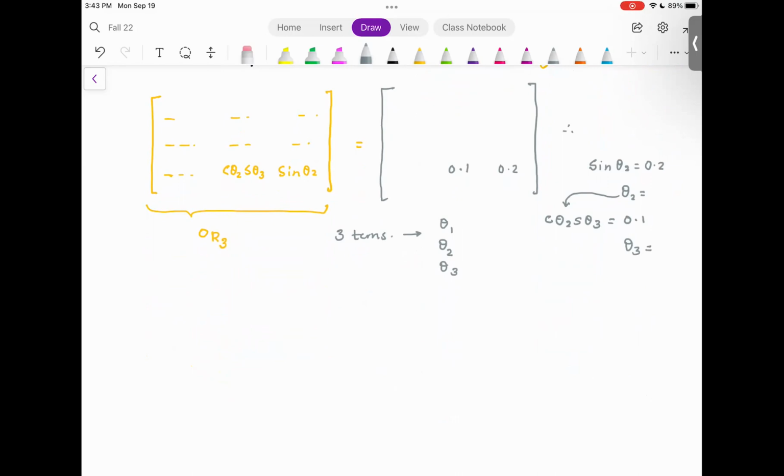maybe in next class. The next point which I want to emphasize is if you want to find out omega x, omega y, and omega z, these are the angular velocities. That goes without saying that omega x is about i naught, omega y is about j naught, and omega z is about k naught.